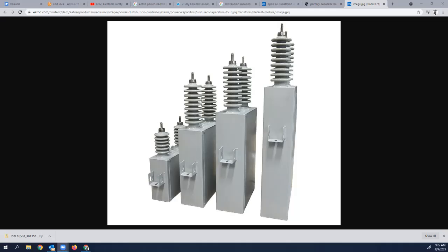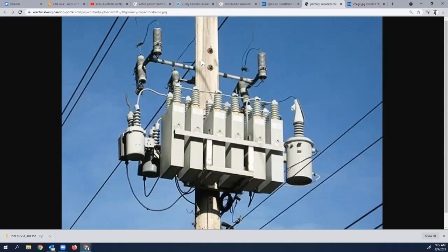And really, you don't need to know as much information about the kVAR itself as you do the sizing. You as an installer are going to get a work request that says, I'm going to need to install a capacitor bank that has a total of 1200 kVAR. And remember from this picture that we had before, capacitor banks are installed on all three phases all the time. So I've got one switch, one switch, one switch that's attached to a phase. We'll talk about vacuum switching here in a moment.